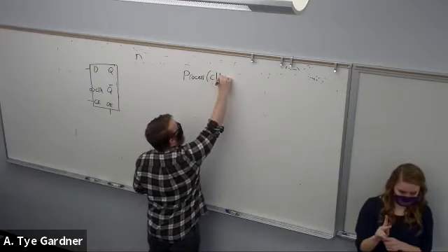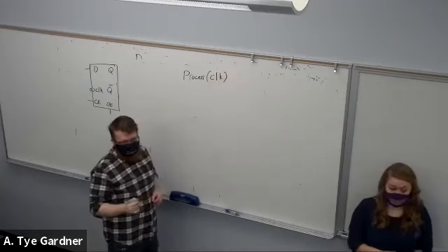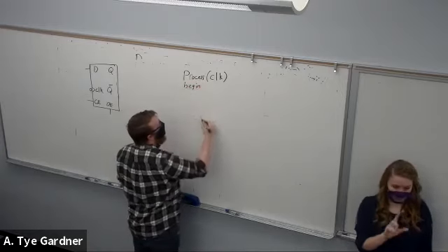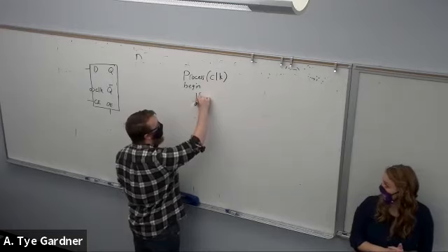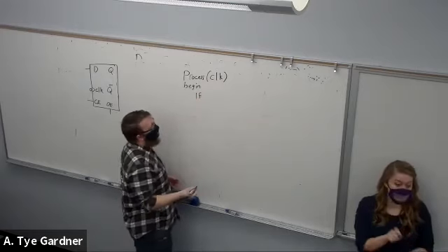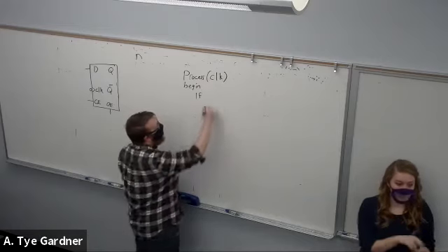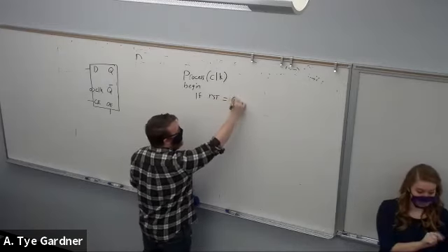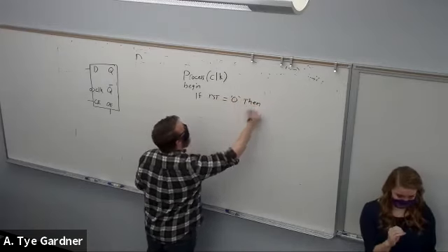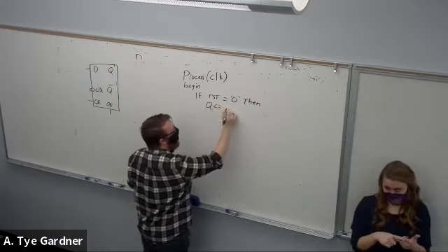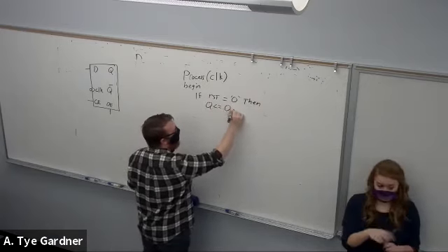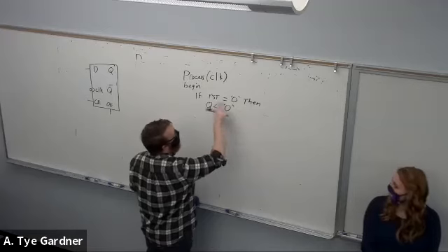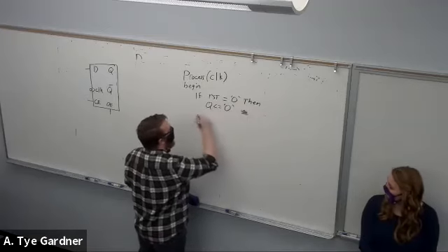So that's the only thing I'm going to put in the process sensitivity list. Then I can do conditions. So it says something like, well, let's do a reset and an enable. If reset is equal to 0, then Q gets assigned to 0. This, I'll do the else over here.